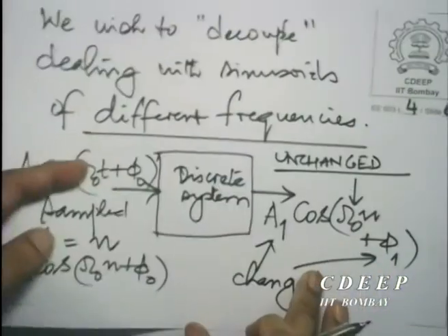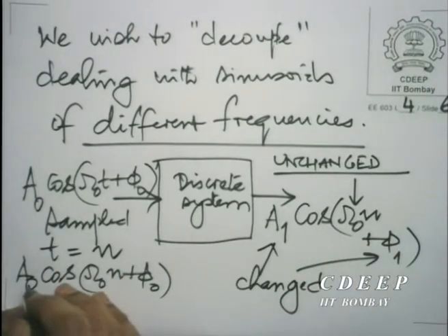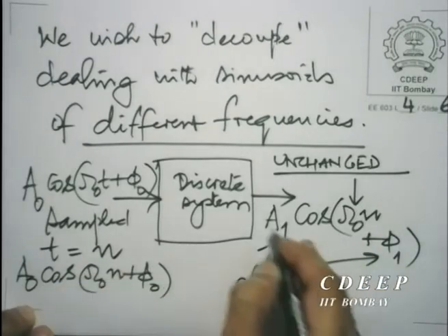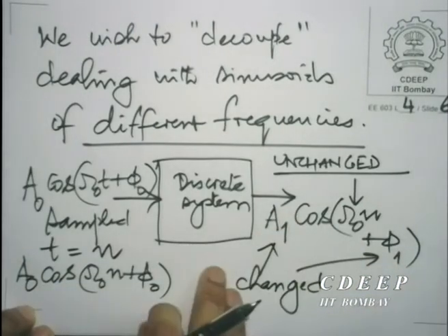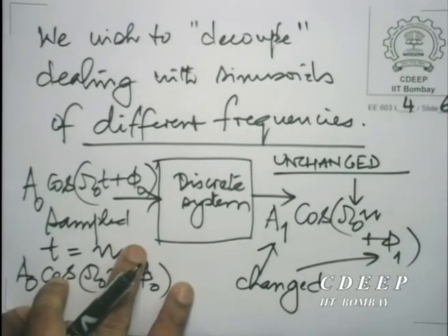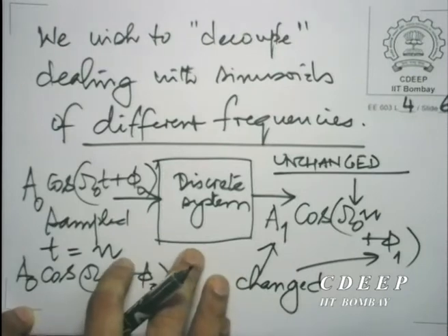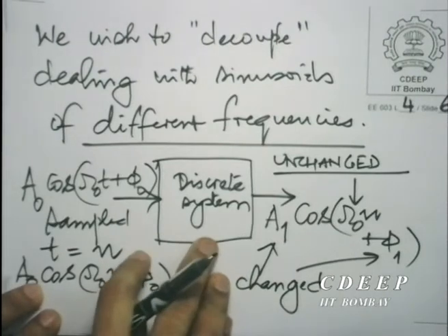You see, take this very situation here. Let us assume that you are able to do this for whatever reason, right. I am able to get a sine wave of the same frequency and with a possible change of amplitude and phase. Even so, when I take a ratio of the output to the input, the ratio is not a constant. The ratio of course depends on n. In fact, you can write the ratio in a complicated way, right? But the ratio depends on n. What I want to do is to see if I can describe this system at that particular frequency by just a ratio.